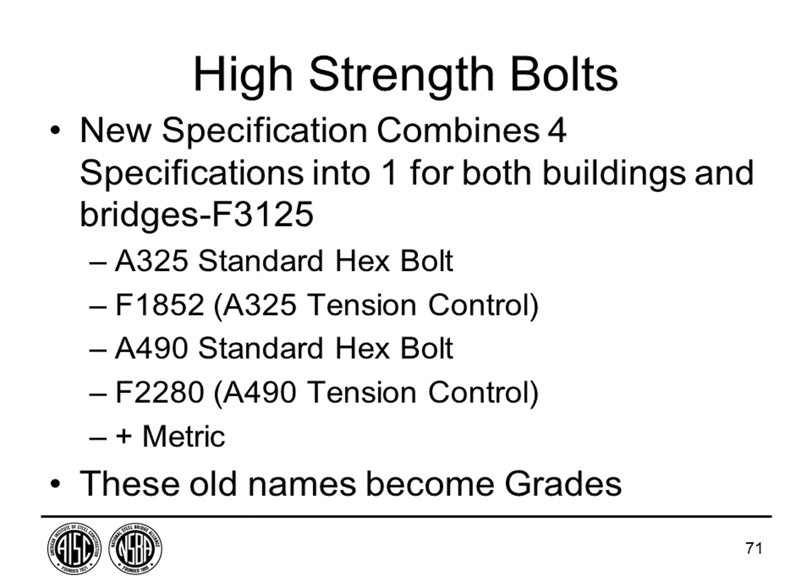But I think what you'll find is that if you're having that problem, the plates weren't drawn up and you had gaps. Either your plates weren't flat and you weren't able to bring them up at the edge, or the bolts weren't properly installed. Because I think if they're properly installed, that's not a problem. We've got an awful lot of weathering steel bridges out there that haven't shown any of this. But you have to watch the edge distance and you have to install them properly.